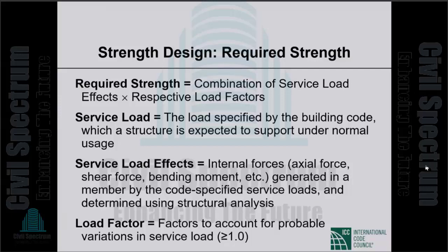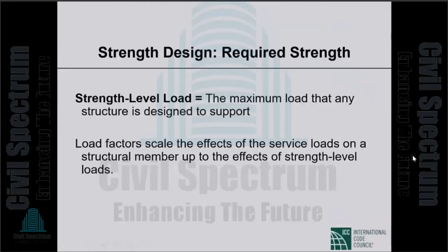Now, what is this design strength? Okay, before design strength, the factored loads that I was talking about are also called strength level loads, the maximum load that any structure is designed to support. Load factors scale the effects of the service loads on a structural member up to the effects of strength level loads. I think this is all pretty understandable. Okay, service loads and strength level loads. When we apply load factors to the effects of service loads, we bring them up to the effects of strength level loads.